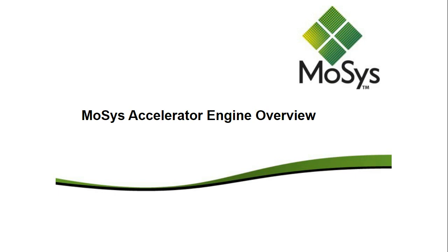And MoSys, which was an IP company originally. MoSys invented the 1T SRAM cell, which was a memory cell that was innovative at the time and still is. Very compact cell size, increased speed, and better soft error rate performance than traditional 6T SRAM cells. So that 1T SRAM cell was the building block of TSMC's embedded DRAM process.